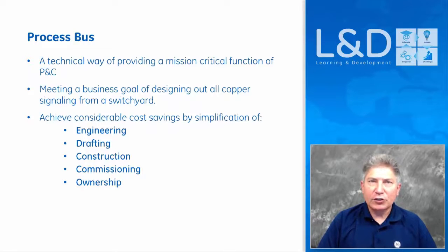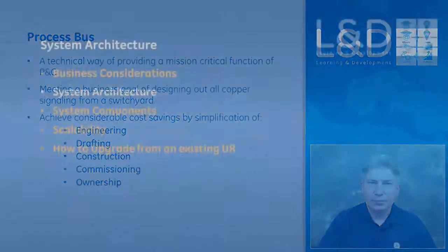61850, its goal is to design out all copper signaling between the switchgear and the switchyard. The other thing that this protocol does is it tries to find achievable ways, cost-saving methods, by simplifying engineering, drafting, construction, commissioning, and ownership.